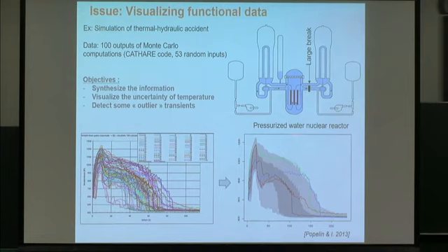If we have a large break on the cold water, we will have a big problem, because the water level will decrease, and so the fuel temperature will increase. So we have to make some exercise on this, not a real exercise, a virtual exercise, to understand this accident.